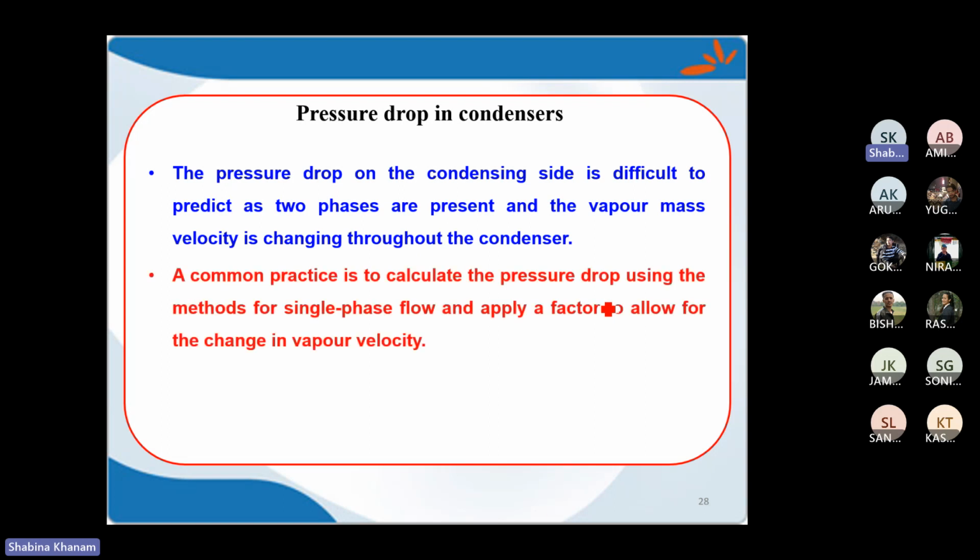So when I'm considering this, we will calculate the pressure drop on the condensation side considering single phase flow, and then that would be corrected by some correction factor.